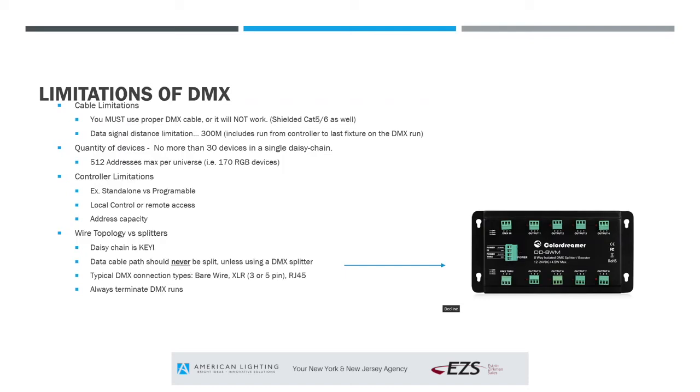And on the Prism side of things, we will generally include a DMX terminator, or however many terminators based on however many runs we have. If we're using a DMX splitter and we have 5 runs, we're generally going to include 5 DMX terminators. So most manufacturers should be including those if it's not part of the system or the fixture itself via a switch on the fixture.